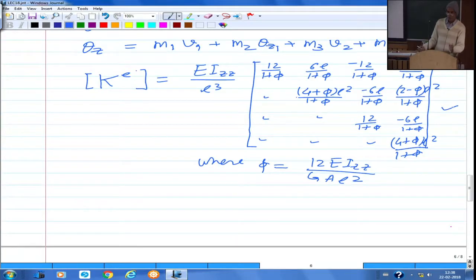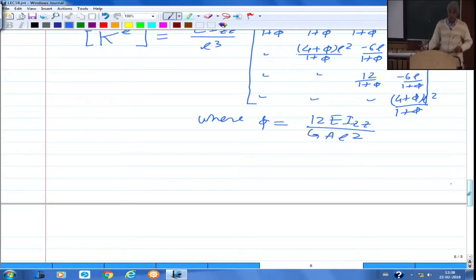So then the third aspect is, so is this clear how we are deriving these shape functions from differential equations, and obviously differential equations are basically connecting the two variables v and theta z, so we get the interconnected or interdependent interpolation, and the advantages I already discussed. The third method to eliminate shear locking was reduced integration.